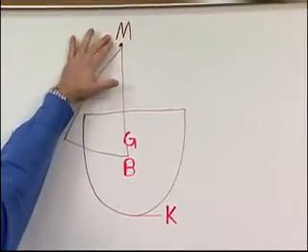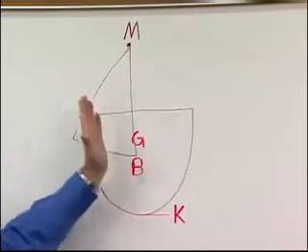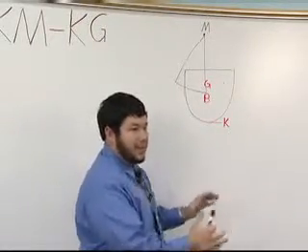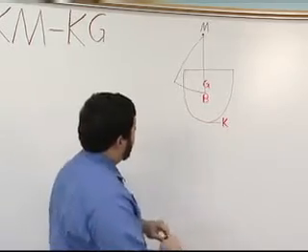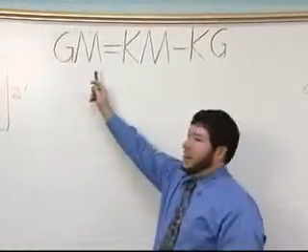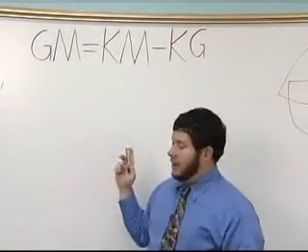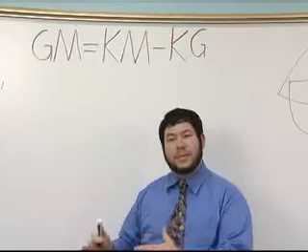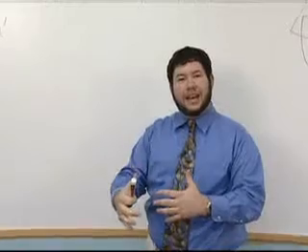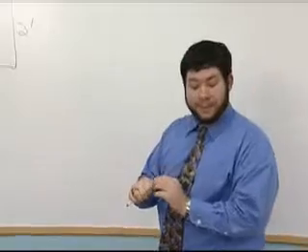The metacenter is this location up here, and basically that's the location that the vessel moves about for small angles of roll, and actually in the longitudinal direction it trims about this location as well. So the way we calculate that is based on the formula GM equals KM minus KG, and we'll break down how to calculate each of the pieces of this. Some of these calculations you've seen how to calculate in other sections, so we'll reference those, but we won't actually calculate them again.